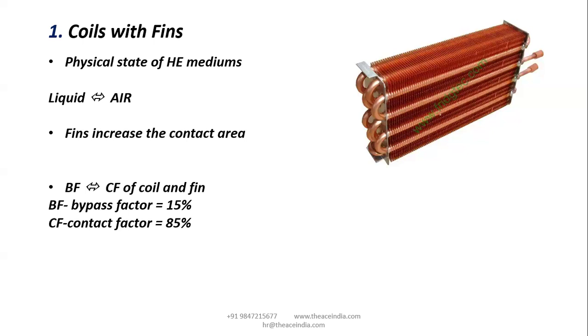The flow takes more time to exit at the out point of the coil structure, isn't it? That means we can get more heat exchange with the air. And you can see the fin arrangement. Fins are used to increase the contact area.